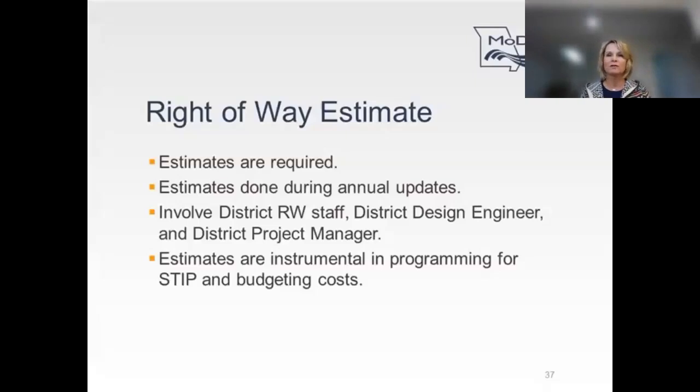Stage 4 is the final right-of-way plan phase. Plans are submitted to right-of-way staff for review and final adjustments before meeting with the property owners. At this time, the final estimate is prepared and reviewed to determine if program cost is appropriate or if adjustments should be made. This phase should be completed at the 2 or 3 year out STIP mark for construction. If the final plans are not submitted until the current project year, the STIP will need an administrative approval to increase or alter the right-of-way funds or to change the scope of the project.